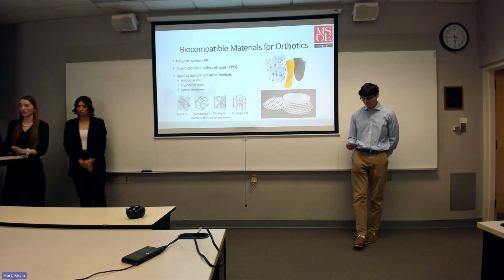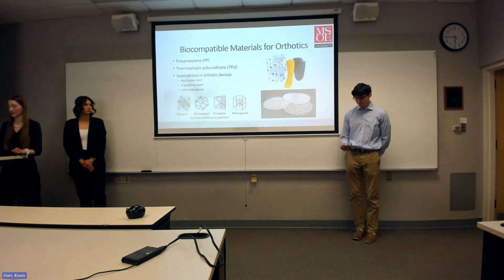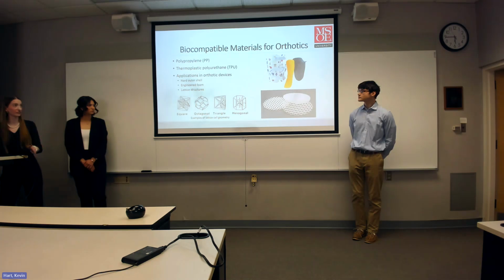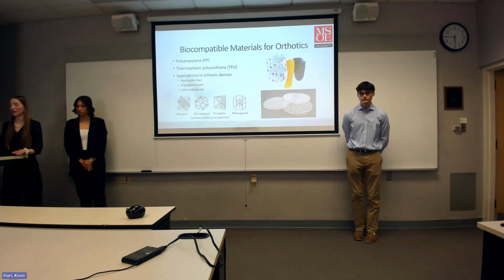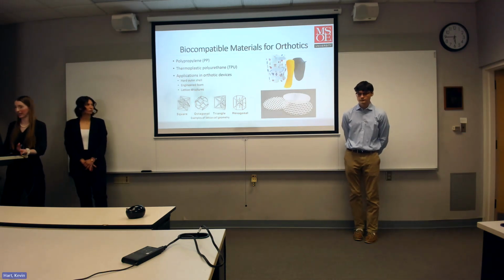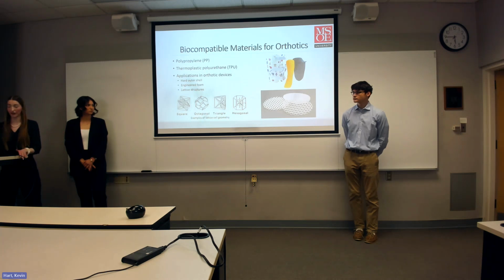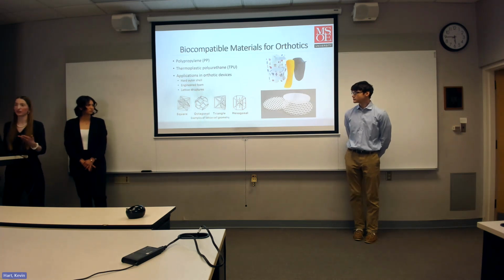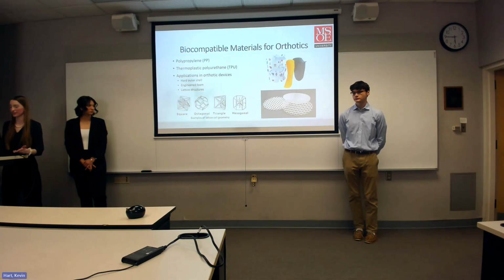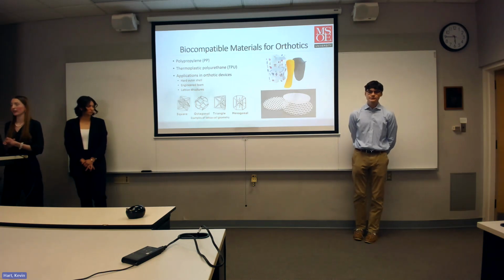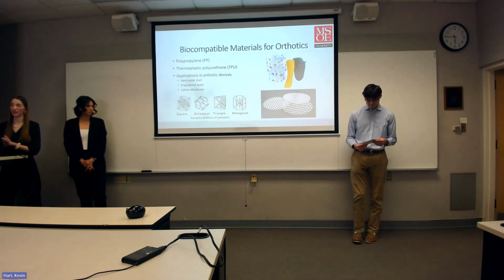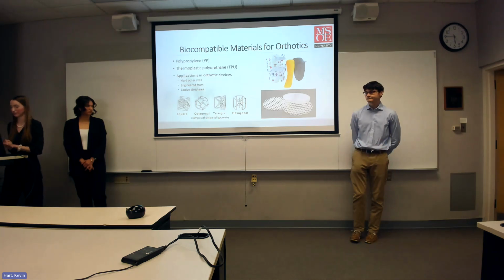Orthotics utilize polymers in various parts of their design, such as the hard outer shell, as you can see in the image in the top right, as well as the inner foam liner of the device. TPU has been used in newly developed engineered foam composed of lattice structures, similar to the image in the bottom right there. These reduce the weight of the material while maintaining the stiffness and strength, but also improve the breathability and airflow of the foam, which increases the patient comfort, therefore increasing the patient compliance with the device and therefore the effectiveness of the treatment.